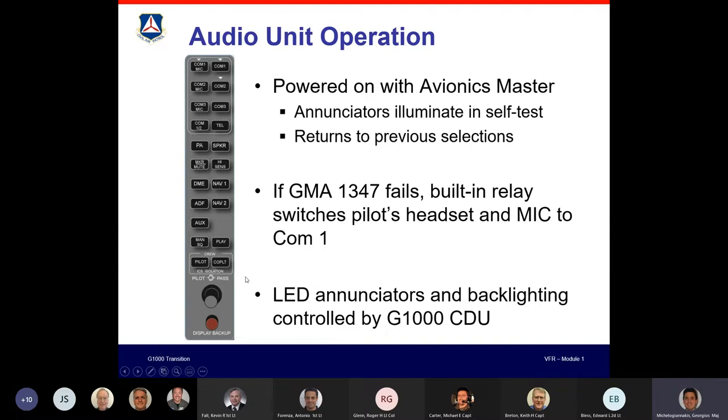And then you have some other buttons. Some of them don't particularly work because of the configuration. But aux is the Becker. I don't think our planes have an ADF, but they do have nav1 and nav2, so you can listen to the Morse code of the VORs. The play button unfortunately doesn't work. Normally the G1000s can replay the last so many seconds that came in from the radio, but that is disabled for us because we have 2 audio panels.